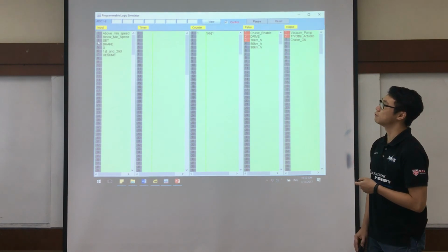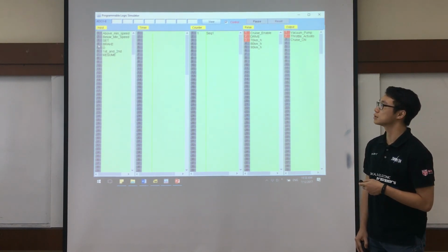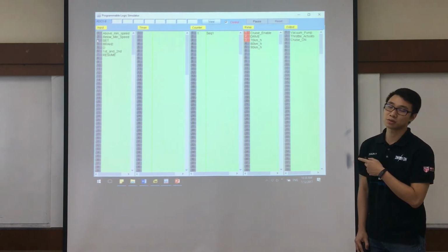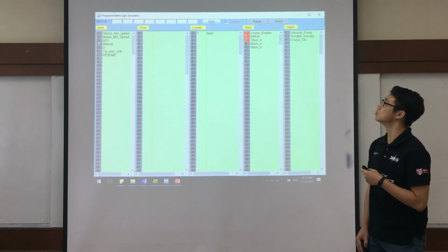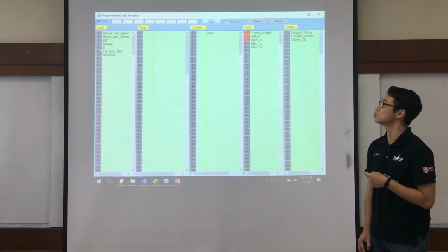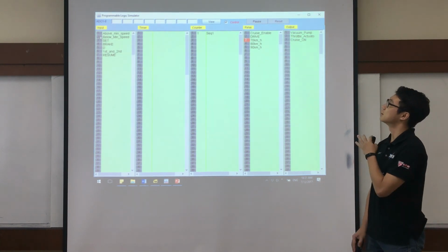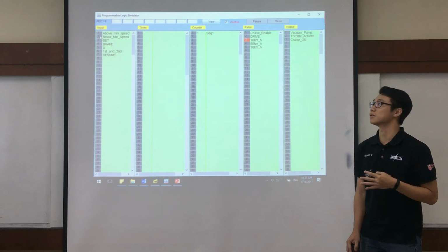We can see that if we want to stop cruise, we can press brake, and this will stop cruise. Another way to disable cruise is by disabling one of the requirements of cruise, which is either the first and second gear, which disables cruise, or we can also press the minimum speed to show that the car is below the minimum speed required for cruise.